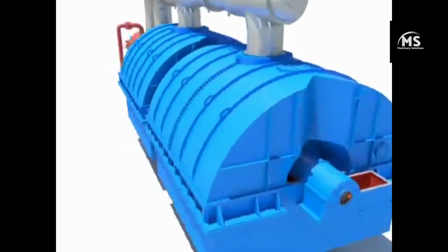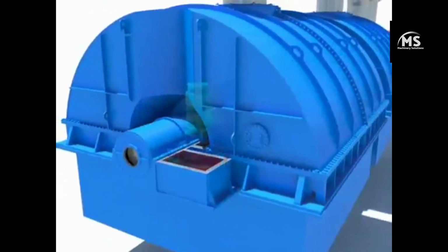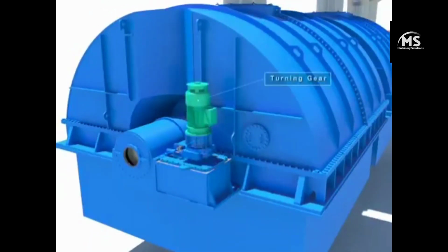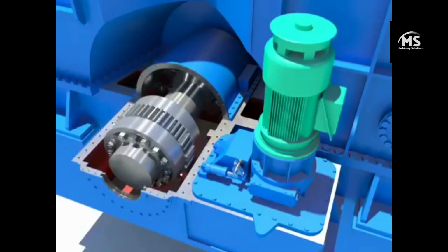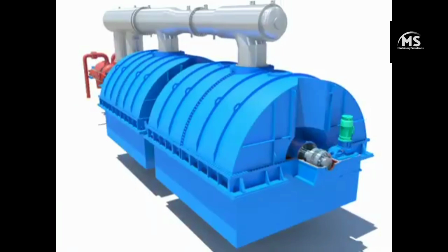The turning gear smoothly makes the speed increase when the steam flows in by slowly rotating the turbine axial when the turbine stops or during the period for starting preparation. Also, it is installed to constantly cool down the turbine inside parts.